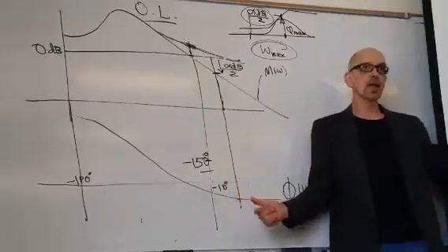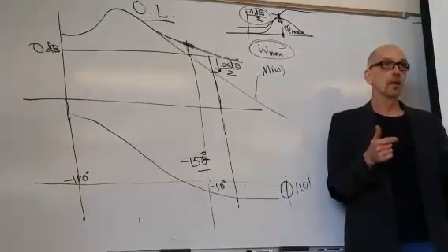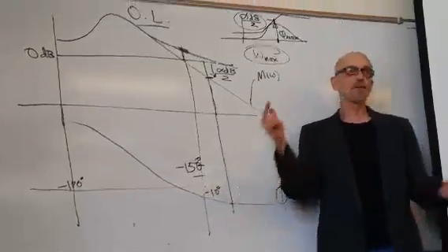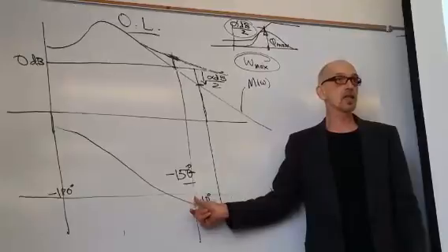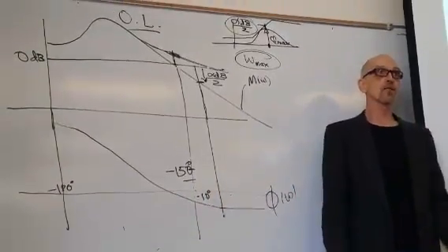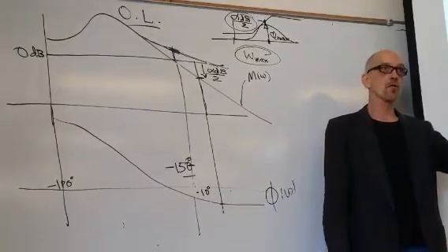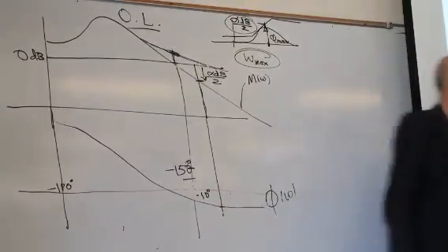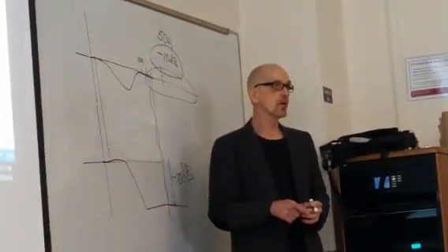Remember, the lag compensator has an omega 1, omega 2 as well, right? And in fact they flip omega 2 and omega 1. But this is the one equation. It says that this guy is 50 times my lower frequency of my lag compensator. That's one equation. So you find that first frequency of the compensator. You also find from its alpha the omega 2 over omega 1. And now you have your two equations and your two unknowns.